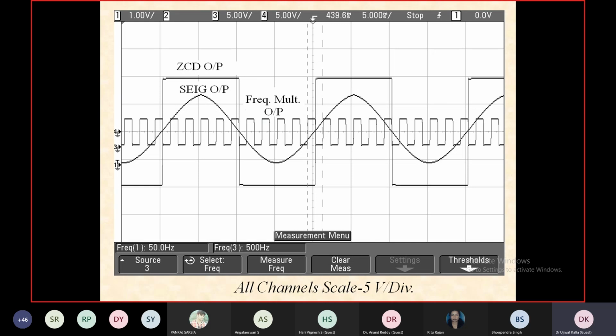This is the main requirement in almost all digital and analog control systems. Even when you are using digital controls, you should take care whether the input and output are in phase lock or not. If the phases are not locked, then your multiplier will not work exactly, the resolution of your control will become very poor, and your steady state error will never be zero. Even if you are using a PI controller, your system will become so unstable that you will not be able to get a perfectly stable system.